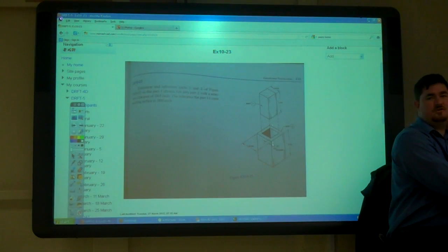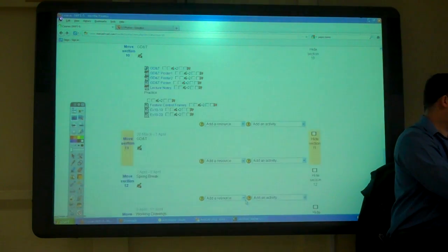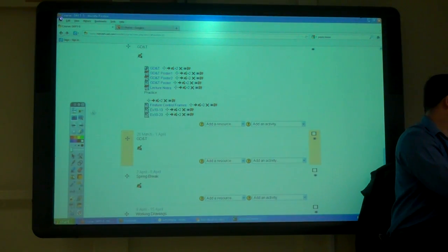And then here we've got two basic parts. You're going to make it so that they always fit together with a minimum clearance of 0.005 of an inch. And then it tells you what the tolerance for this surface is. Or no, the tolerance for that surface. So the size tolerance is 0.06 for this. And you have to readjust the sizes to make it fit, so that you always have 0.005 of an inch clearance. So we'll do one that's kind of like 1013.